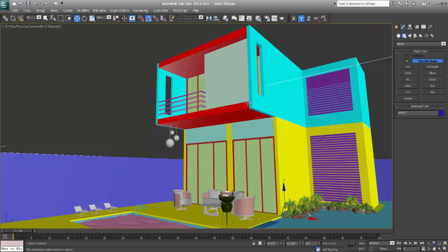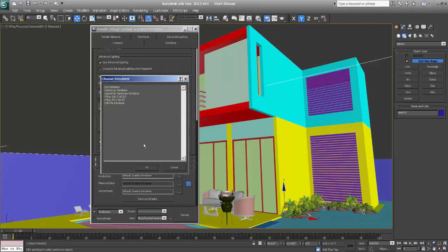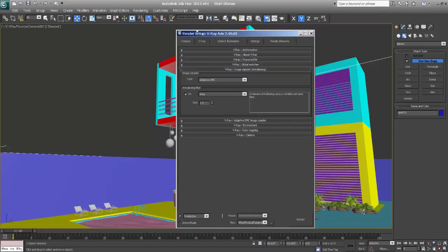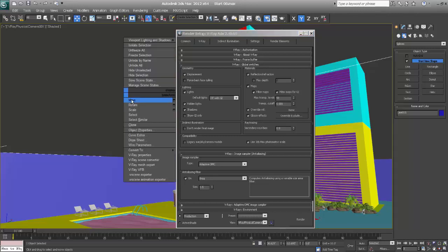But before texturing, I always do my test renders of, say, an off-white with a texture, so we can see how and where the mesh is going. So it's very easy. I'll go to settings and I'll take first Vray render and global switches. On override material, I'll go to my material.